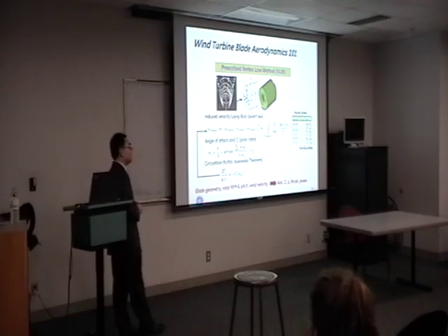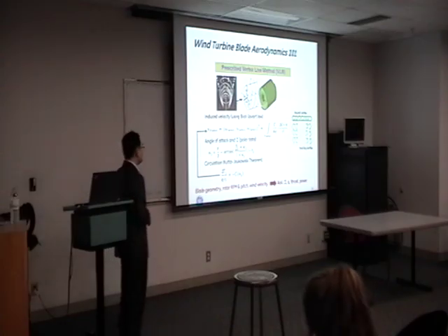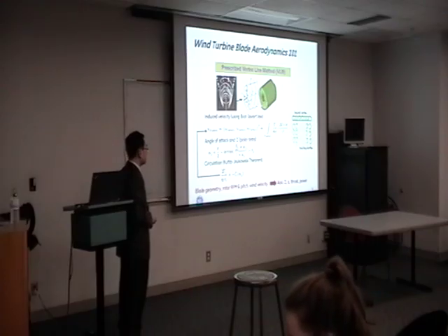But the input and output are the same. If we know the blade geometry, rotor RPM, pitch angle, and wind speed, we can compute angle of attack, CL, axial induction, thrust, and power.